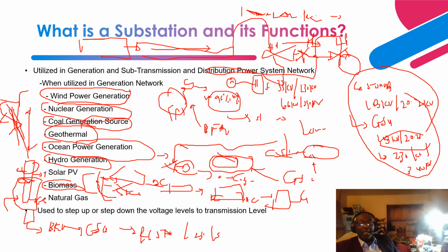So finally, as the steam leaves the low pressure section of the steam turbine, it goes into a condenser, right? On the walls of the condenser is cold water that is fed into the walls. So as the steam gets here, it is, I would say, about 60% dry and 40% moisture. As it impinges on the wall of the condenser, it converts into water.